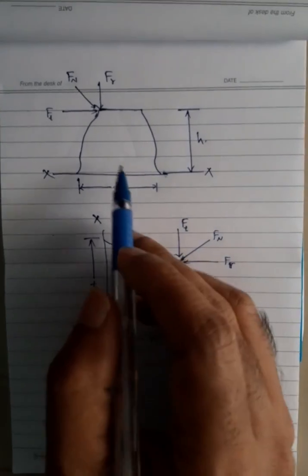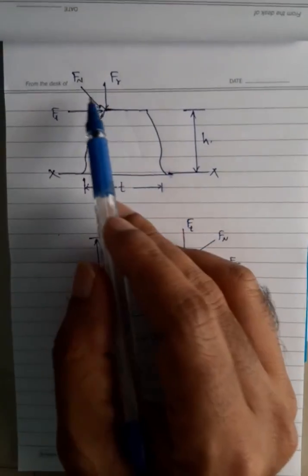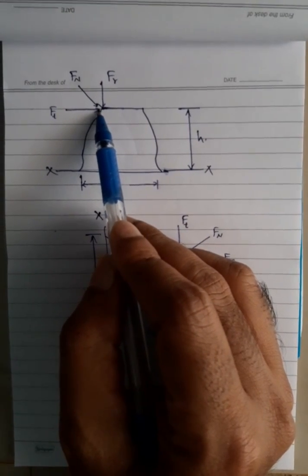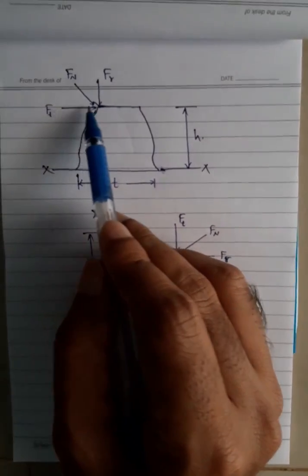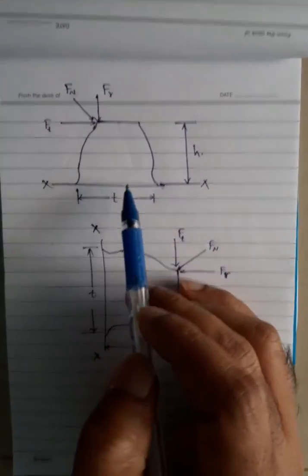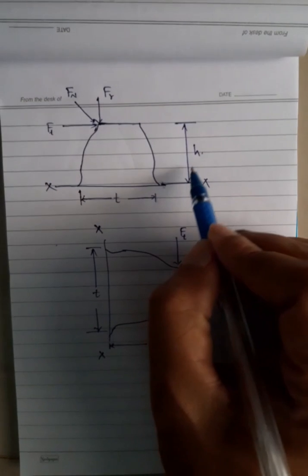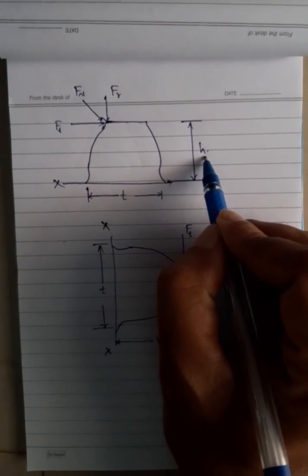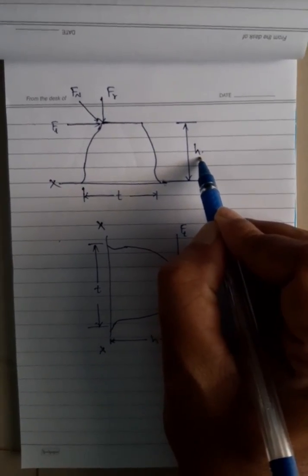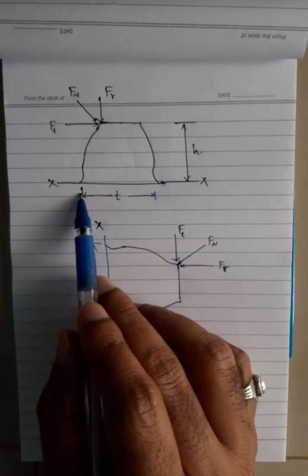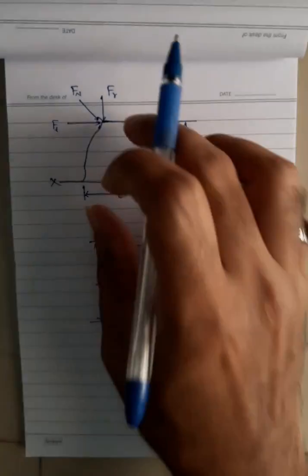To start with the Lewis equation, let us consider a single gear tooth which is subjected to the normal force Fn, which is resolved into two components as radial force and tangential force. This tooth has a thickness of t, which is shown at the base, and it has a height of h, and we already know that each tooth has to be considered as a cantilever beam. When I say cantilever beam, one end of the tooth has to be fixed and the other end has to be free. So if we rotate this figure